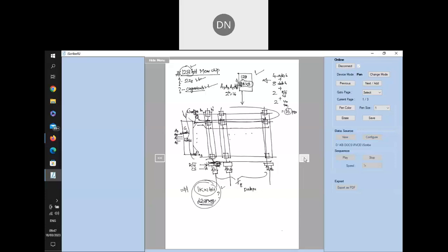We'll take a little bigger size now. Let's say I will take a 4 megabit chip, which is commercially available. The organization of this chip is 512 kilo into 8. We know that 2 into 512k means 1024k. So if I say 512k into 8, I'm going to get 4 megabit. So now this is the organization.